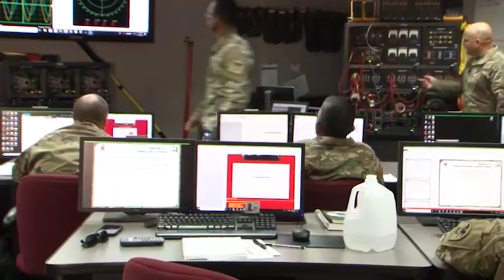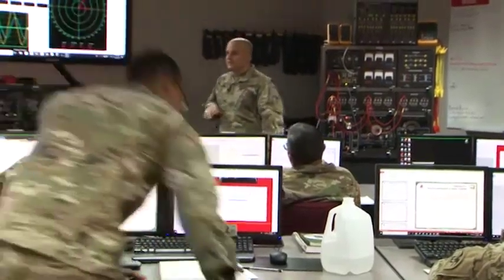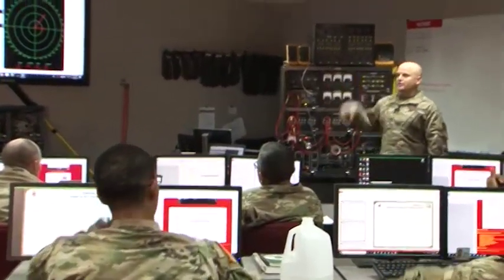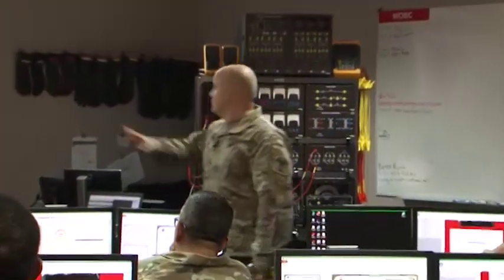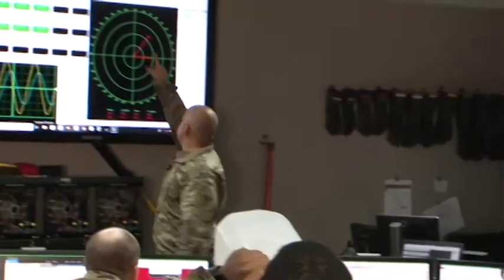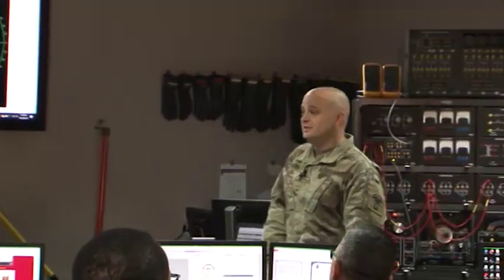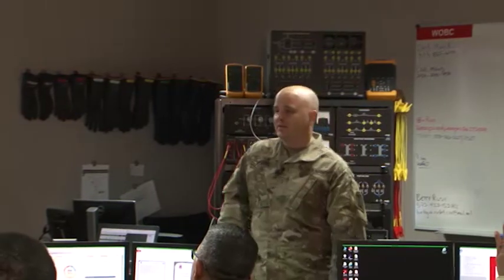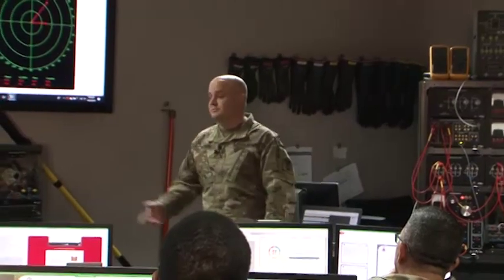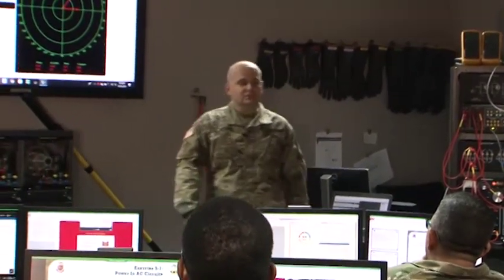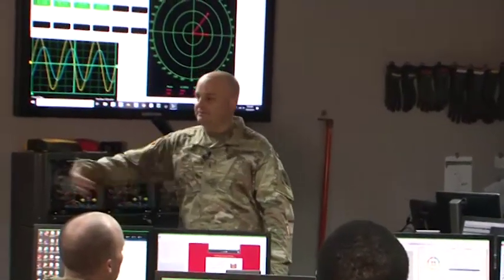Gold star. All right. So now, we said that inductance and capacitance, again, they're kids pulling in different directions, right? Capacitance is pulling in a complete 180 degrees out from inductance. So if I was to add some capacitance to this circuit, what's going to happen? What's going to happen to this angle, do we think? Closer to 90? It depends on how much you add. You're adding reactance. So I've got some resistance in there and I got some capacitance, and my resultant is somewhere in between the two. All right.